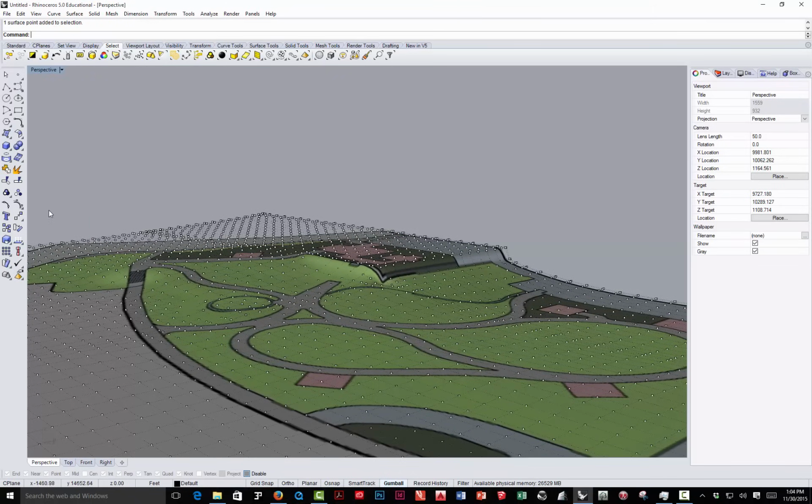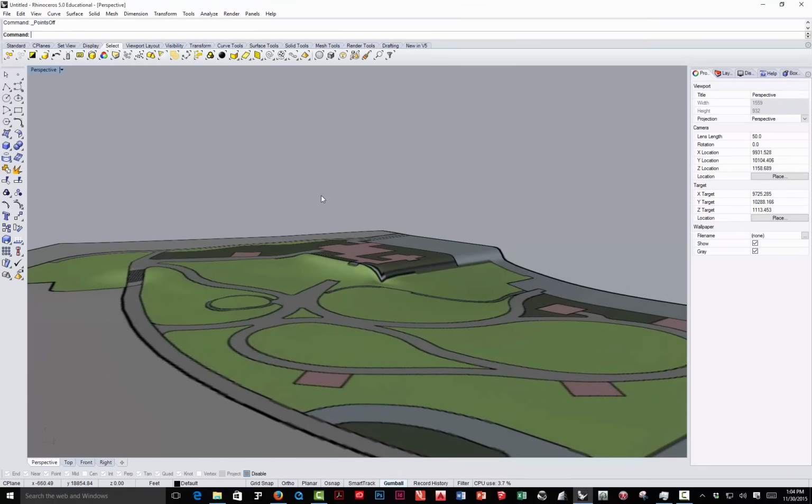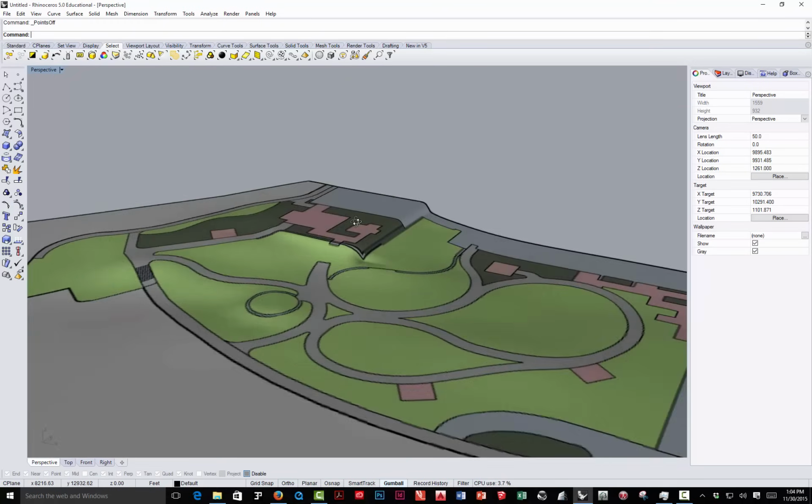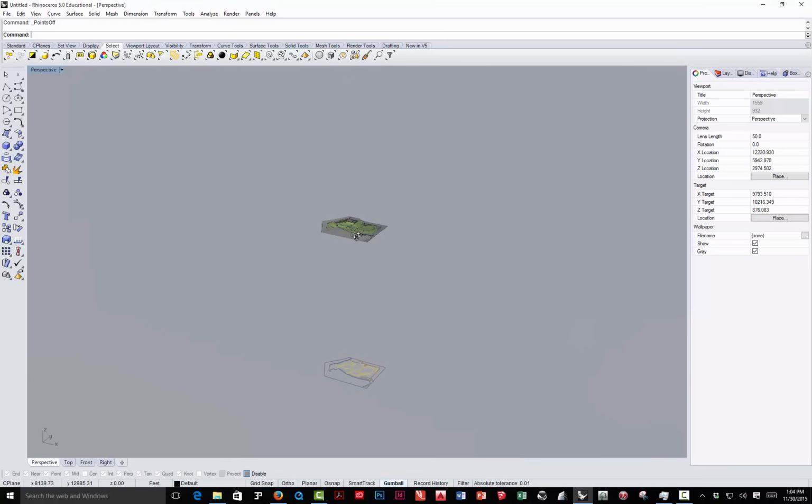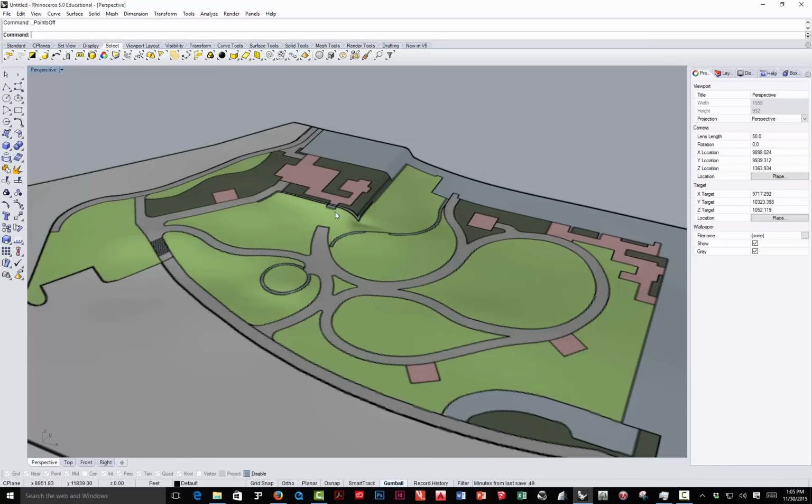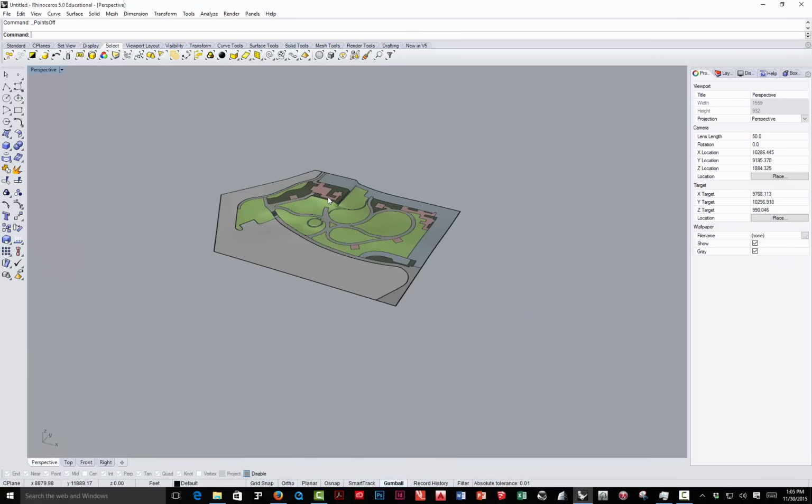And if I want to verify that, I'm going to right click. I'll get rid of that. And now let's just go ahead and jump ahead before I work on the other. It's basically adjusting for the steps here and here. I'm going to do the same thing. I'll do an insert knot to add any more control points that I need. And I'll get to this in this tutorial, but we're just going to do it one step at a time.